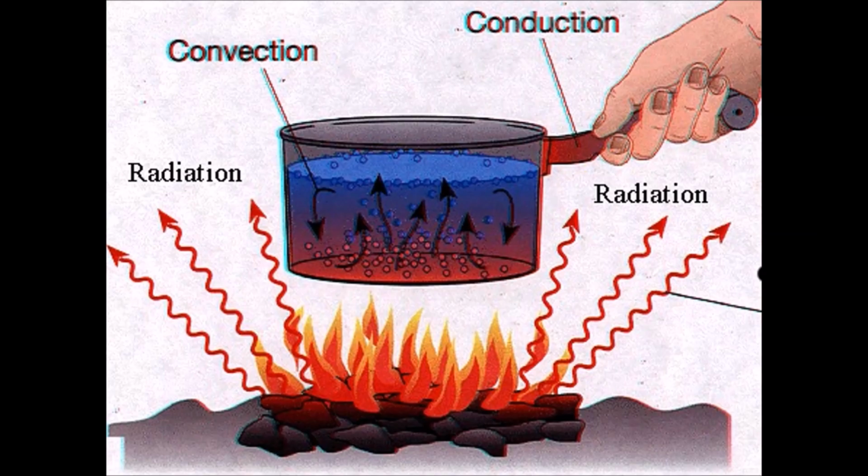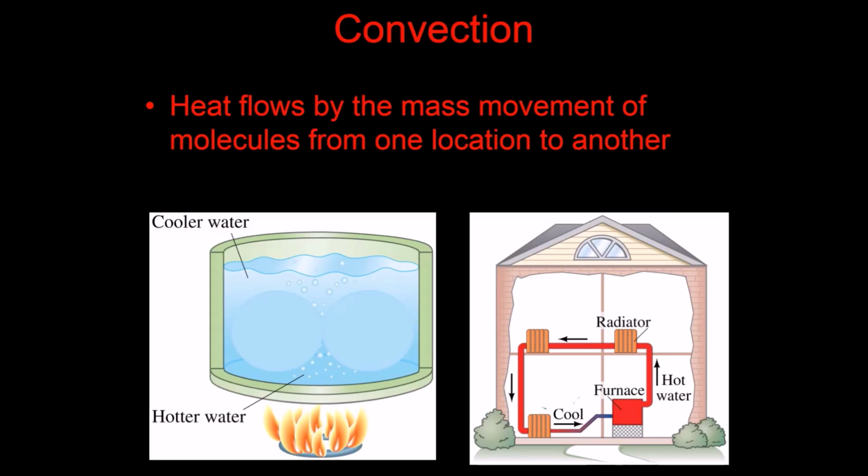So this is the way that convection really works in terms of water heaters and house HVAC systems. So in terms of the water, we will apply a flame to the bottom of this tank. The flame then heats the tank, conducts through, and then sets up convection currents, which eventually heats the water. The cooler water will end up descending, and the hotter water will end up rising. This is very similar to the way that atmospheres also operate, with cool air descending and warm air rising. The turbulence you feel in an aircraft is essentially caused by this exact effect.